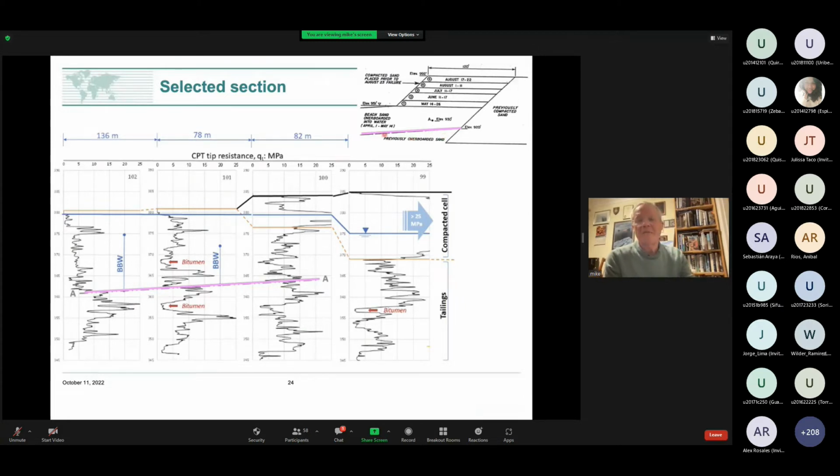So this pink line here from their sketch of 1975, we said, okay, we look at all these CPT data, and I've got 1, 2, 3, 4 CPTs on the screen. These have been stacked by elevation. We went looking through these CPTs to say, okay, I could just about buy a beach in here. So perhaps these 4 CPTs are a reasonable representation. This here, I should have told you, is the current beach above water, and it then goes off into the pond.